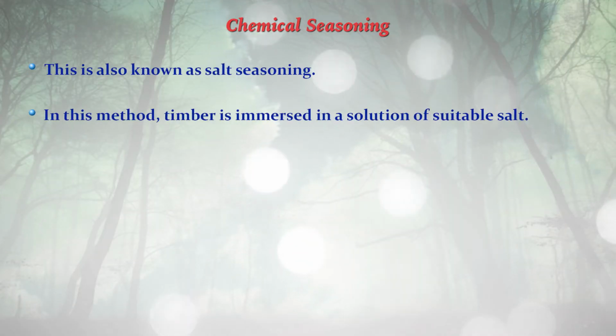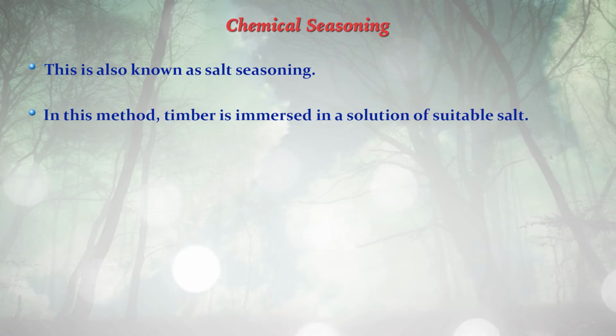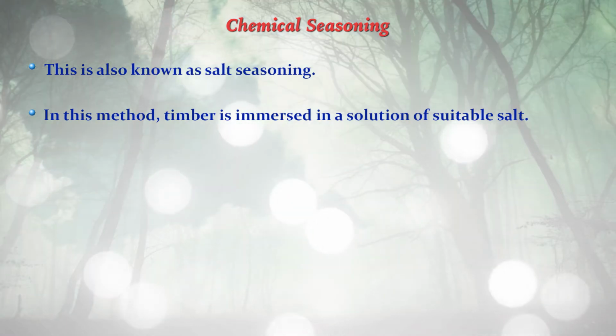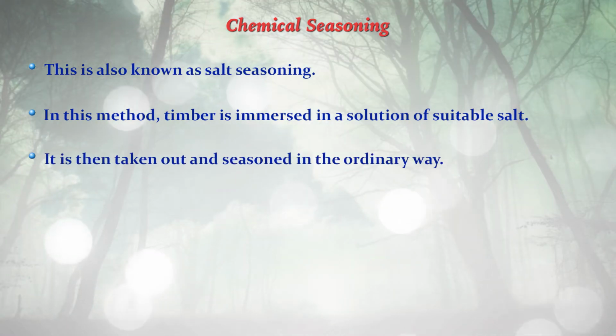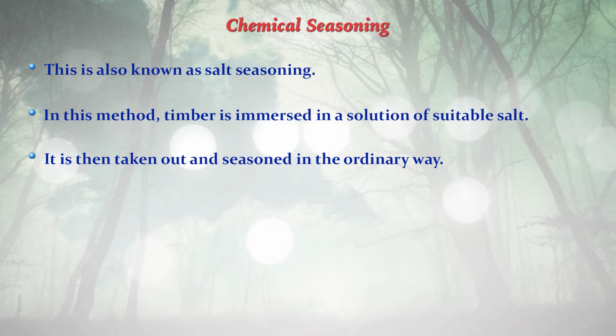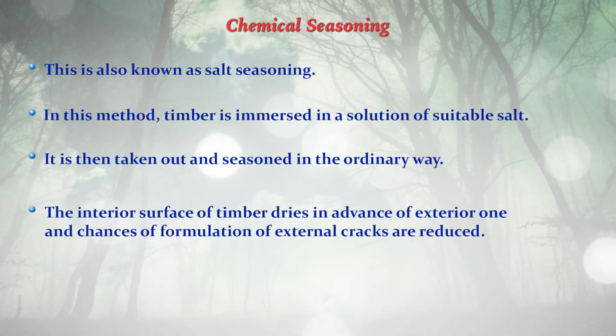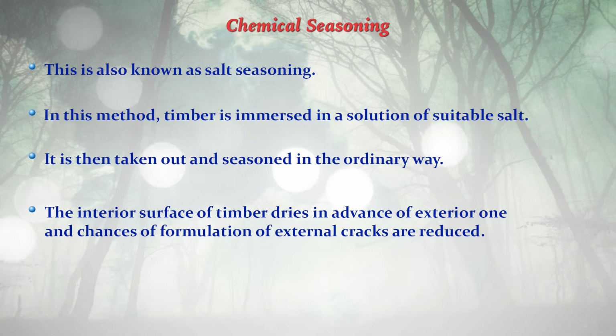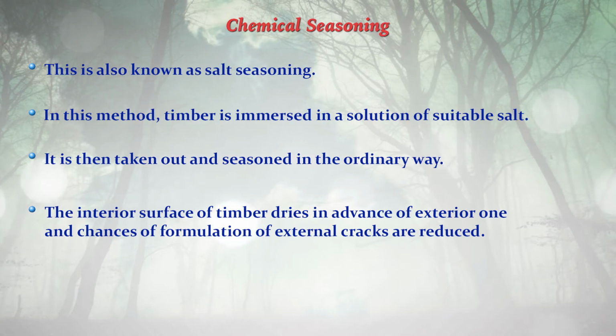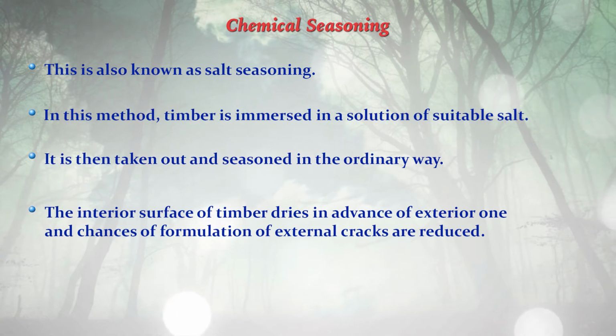In this method, timber is immersed in a solution of suitable salts. It is then taken out and seasoned in the ordinary way. The interior surface of timber dries in advance of exterior one, and chances of formation of external cracks are reduced.